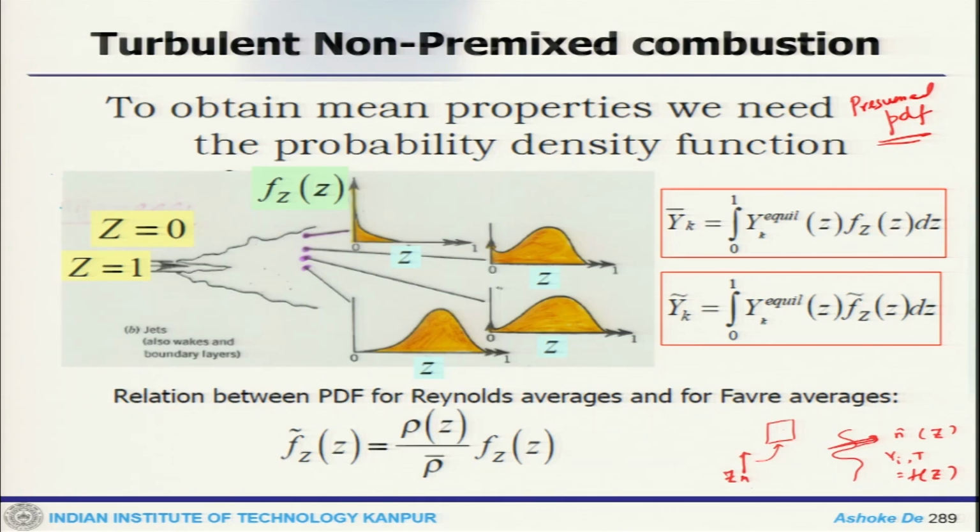But dimension-wise, transported PDF extensions are quite expensive, they are heavy in dimensionality, and that is why we solve in a hybrid approach, where you solve the mean flow field in the Eulerian framework and the transport equation of the probability density function is solved in the Lagrangian framework.